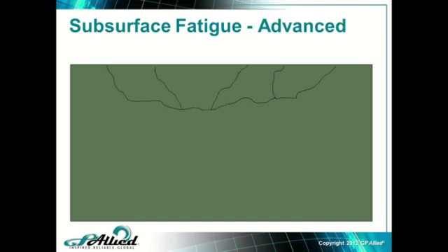So it's still called a subsurface fatigue, but we can throw the word advanced on there if you like. Now, what's interesting here is the energy being given off by this subsurface fatigue, as you might guess, is extremely high frequency, super high frequency. And that is why the ultrasonic instrumentation picks it up so well.